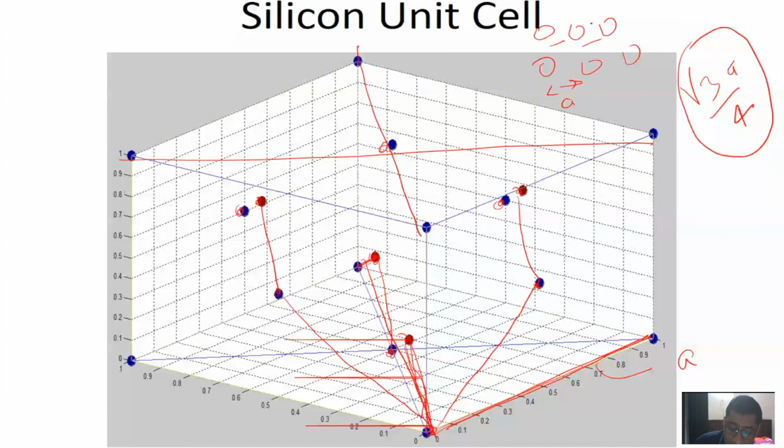If A2 is more than A1, then the upper layer has to be compressed, so there will be compressive strain. If A2 is less than A1, then it has to be pulled, so there will be tensile strain. This strain basically decreases the layer thickness that you can grow defect free, because once it reaches a certain thickness, the force due to this stress or strain becomes high enough to cause the layer to relax.